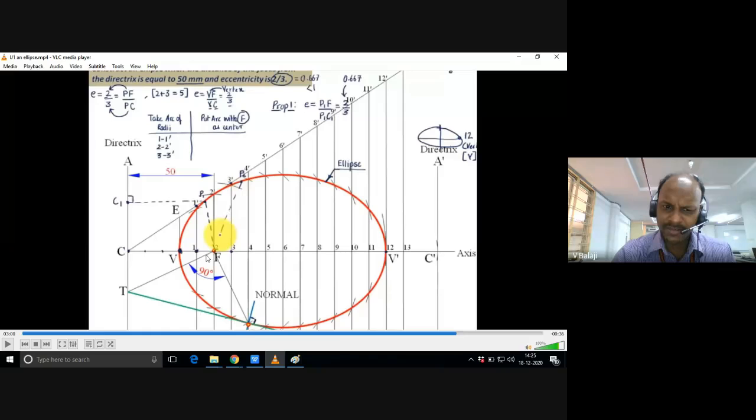For the remaining procedure, this line and perpendicular lines, all other lines, you can use a 2H pencil only, except the elliptical curve. The elliptical curve you draw with an HB pencil, dark. Except the ellipse and the normal and tangent, all other lines, even the axis, directrix, line division method, perpendiculars, extension lines, everything is with a 2H pencil. While writing the numbers 1 2 3 4 and letters, you can use an HB pencil, dark. This is the standard rule for the entire semester.